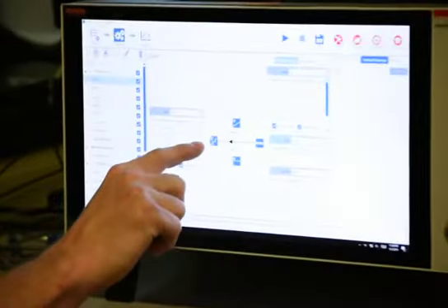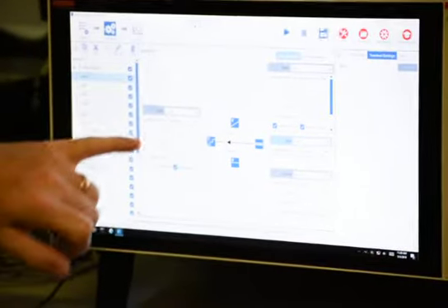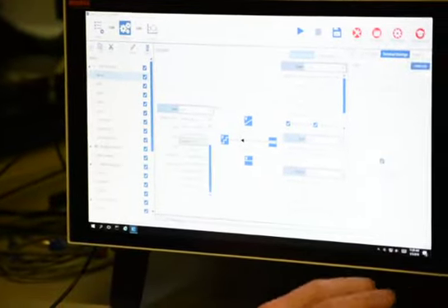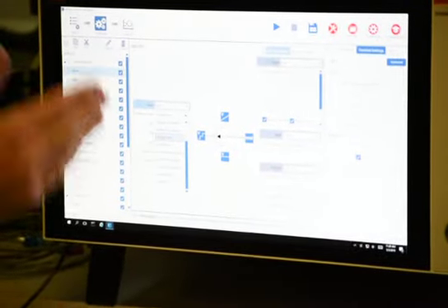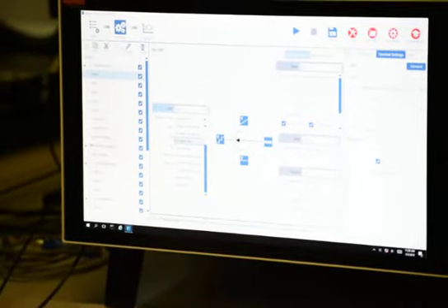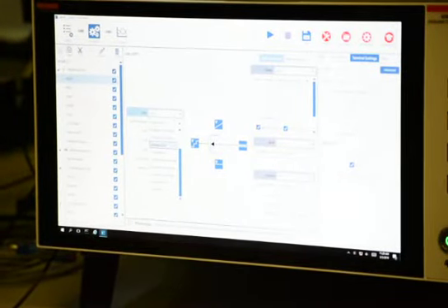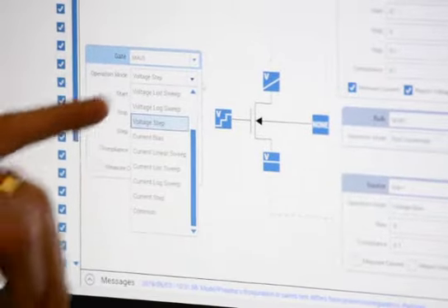So this is showing you. I'm going to do a voltage step, as you can see, for the SMU. I've got a whole bunch of different options. It's supposed to be nice. You all understand these options. You know what a list sweep is. List sweep is just a list of values. You can literally import a spreadsheet into it. So you can do arbitrary waveform generation. It's for the list sweep, voltage list sweep.